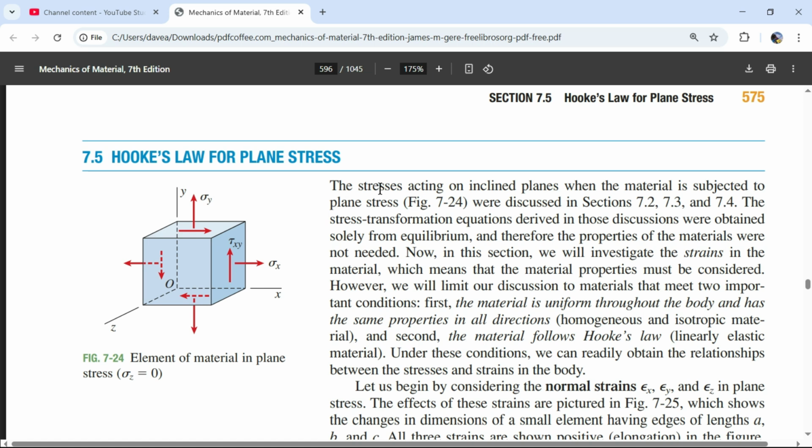I think I was going, I still get confused of chopping a tiny little element. Because if you chop a tiny little element, you can't use the entire force. So it's just kind of fascinating that I can chop through a huge element and find the forces needed to balance that face. And then what happens, though, is you're just going to say, okay, those are the normal forces and shear forces on that face. And so that's where some of the previous chapters in bending stress, if you have a shear force on a face, like at a 45-degree cut, the shear force isn't going to be uniformly distributed because you can't have any shear force at the ends on the free surfaces.